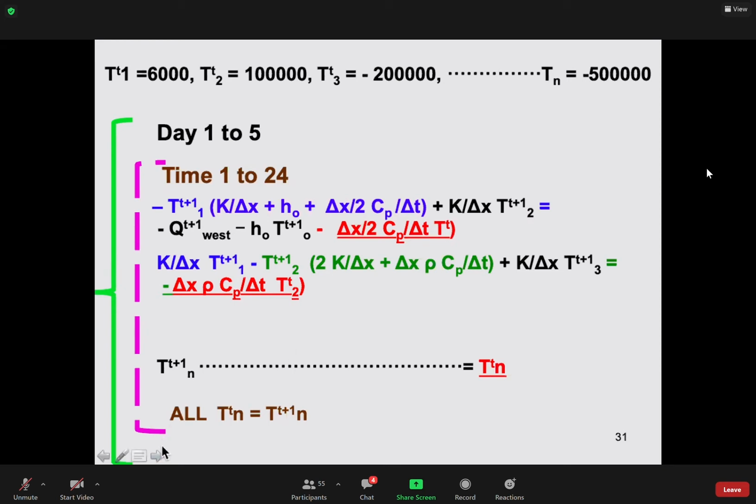Here, after, let's say, 1 day, keep the temperature of one of the nodes. Let's say keep node number 3, and compare today with tomorrow. If the temperature at node number 3 today and tomorrow differs by less than 0.5%, then you can say that your result is converged and you can stop the simulation, okay? But if you'd like, you can run it for 5 days, it doesn't matter, because it takes only 2 seconds to do that, okay? Any question?